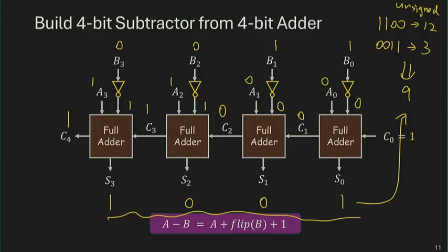So in your hardware, you just have to build a circuit once, with a bit of additional switching or processing logic before your inputs, to repurpose the same hardware for different computations. So let's say you have an area that can fit 8 adders or 8 subtractors. Right now, you can probably put down 7 of these reconfigurable adder-subtractors and be able to realize a much wider range of computations. It gives you better flexibility by being able to adapt your hardware for different purposes.